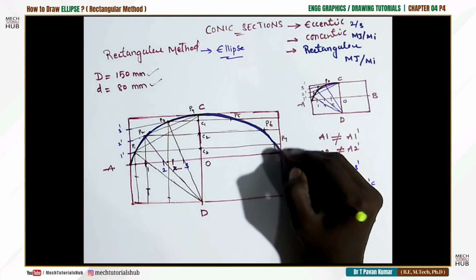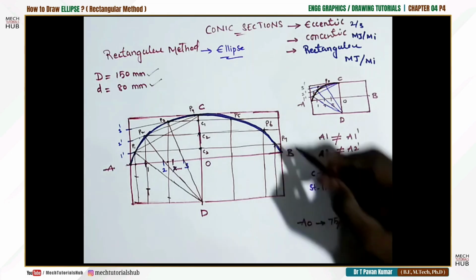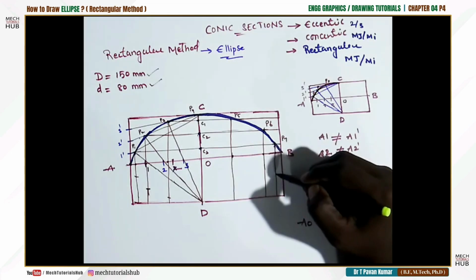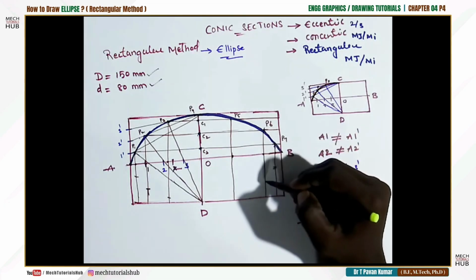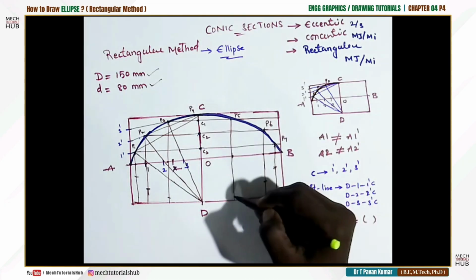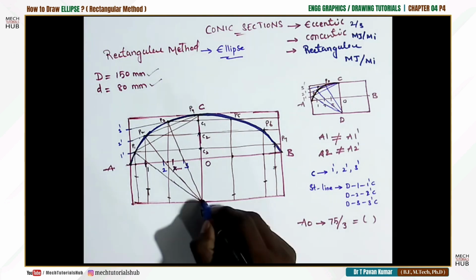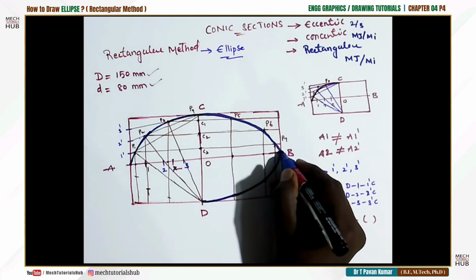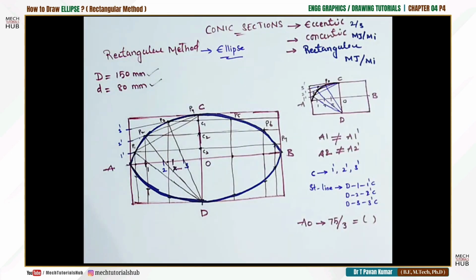Draw locus from here also, vertical and one more vertical. Then again, measure this distance from here and this point, this distance, and make a mark. Similarly, from here, this distance should be equivalent to this distance. This should be equivalent to this distance. Now, with the help of HB pencil, I'll try to join them with a freehand. You have to join with a single stroke, something like this. Similarly, this half. This is how you need to develop an ellipse.